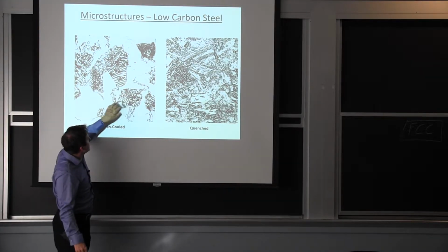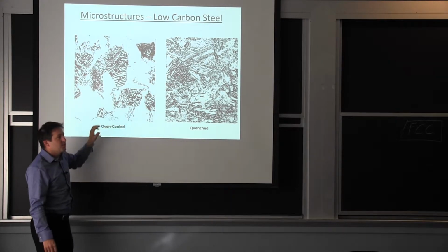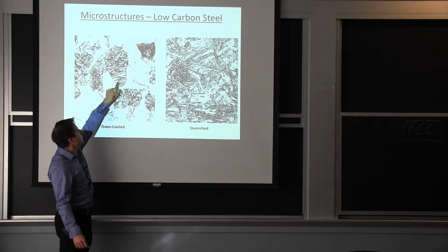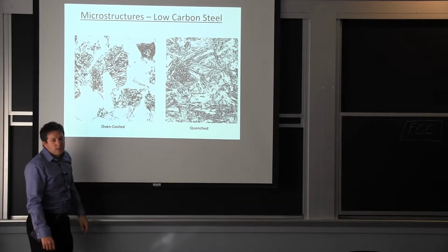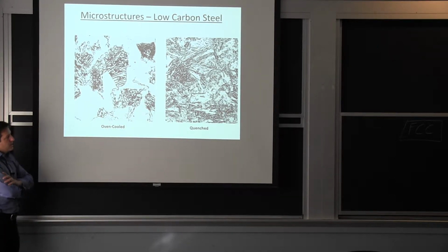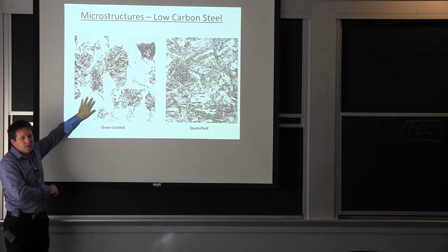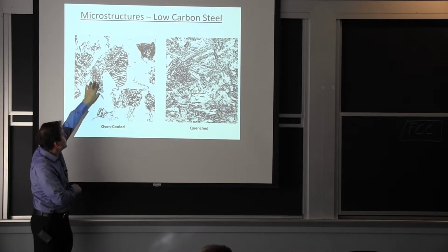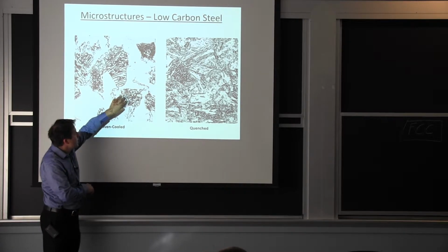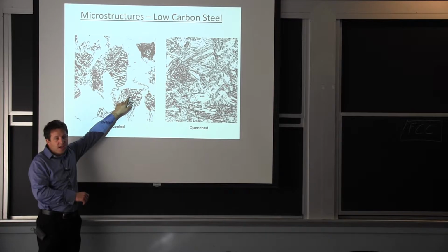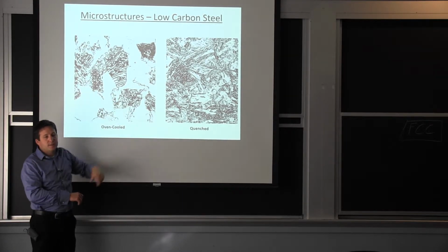well, this phase here is the eutectoid or the eutectic. So it's a two-phase region. It contains cementite, and it also has the almost pure iron phase. So it's a multiple process taking place. The first thing that happens on low carbon steel is you form those. And these are, again, almost pure, almost no carbon in them. It's pushing the carbon a little bit towards the eutectoid, and then all at once you separate the carbon. The carbon goes to the black here, and then you get another white.